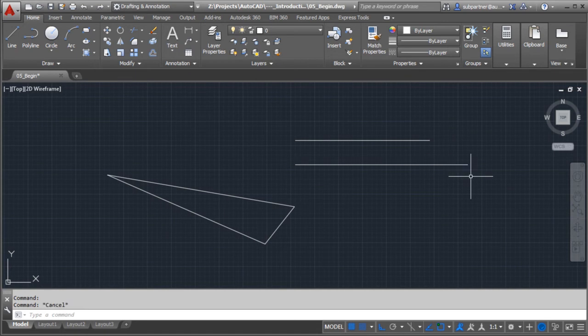Now, what are units? Well, when you're working in AutoCAD, you can set your units to a number of templates. So if I want to access my units, what I need to do is type in a command. Now, what is a command? Where's a command? The command line. You may have heard me mention it earlier. Well, the command line is right down here. Now, we didn't jump into that when we were looking at our panels because we wanted to know where all our tools are. And you really don't use this until you start drawing.